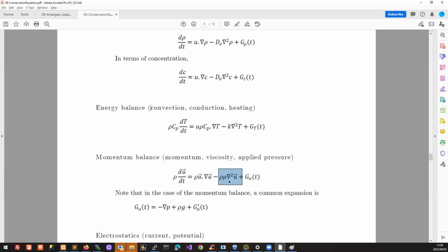And if you imagine honey in flow in a pipeline, then if in the center of that pipeline you've got fluid flowing faster than the rest, you can imagine it's going to drag the neighbors around. So it drags on the neighbors. So that's like diffusion of momentum as well. Your momentum is tending to convect in one direction, but then that momentum, that force, is also dissipated radially as it's contributed to its neighbors. So diffusion of force, this is diffusion of energy, diffusion of mass.